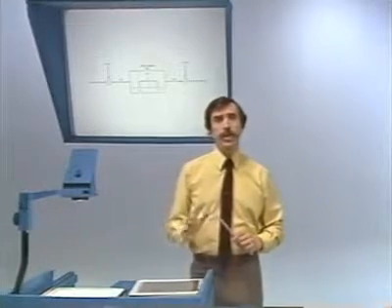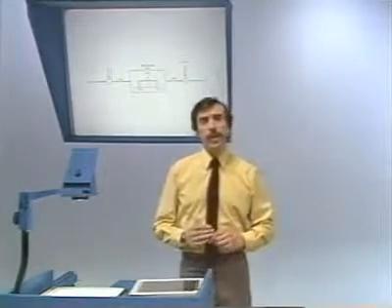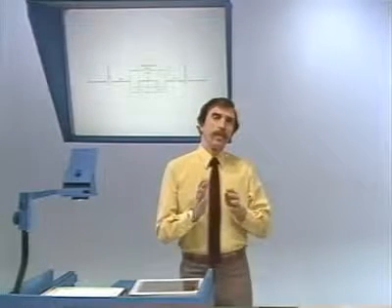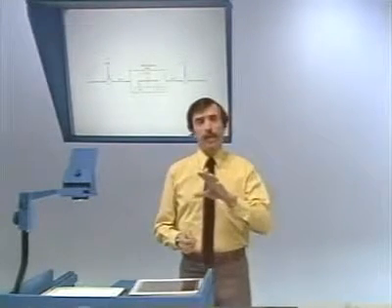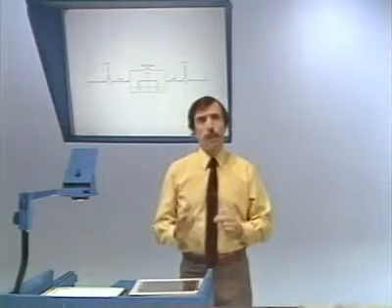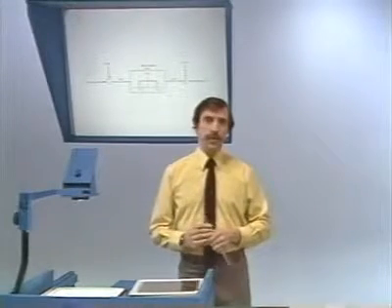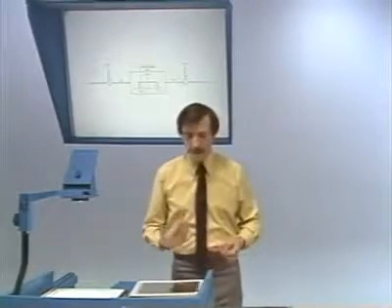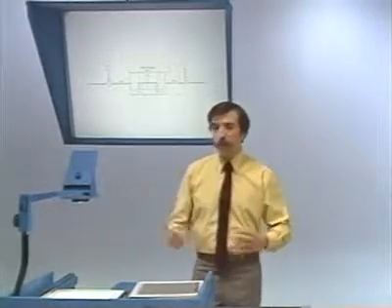And that is the notion of using modulation to permit the application of a very well designed and implemented low-pass filter to be used as a bandpass filter and, in fact, as a set of bandpass filters. And here's the idea.